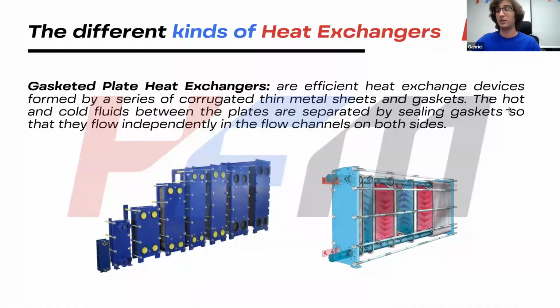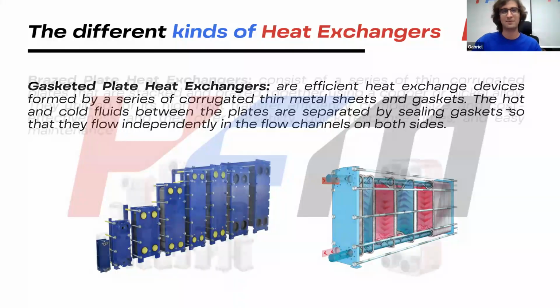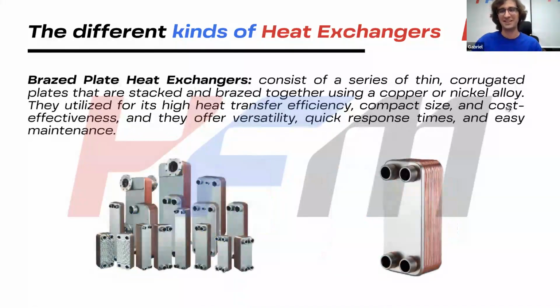But now I would like to talk about another kind of heat exchanger. This is the brazed plate heat exchanger. It's also composed of a series of thin plates, but instead of having gaskets between these plates, sealing the fluids and separating them, the plates are actually brazed together with a copper or nickel alloy. And yeah, they're very efficient, they're very compact.